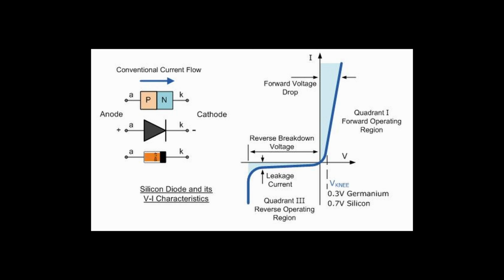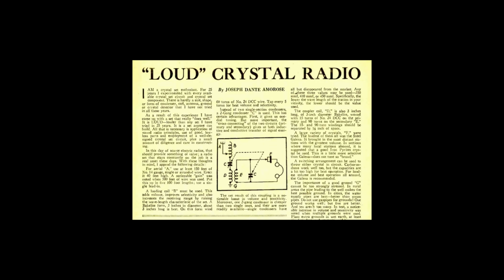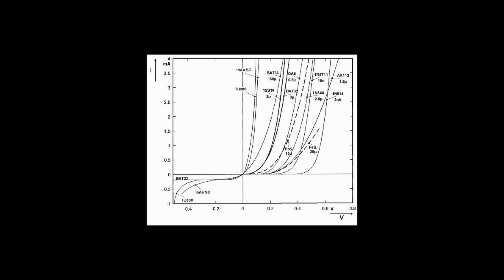My point is that no matter what's happening in the detection process, the diode's being a diode. It's conducting more in one direction than in the other, and it's doing it at a very small signal level. The forward voltage tester in your meter might be a great way to roughly identify whether it's a silicon or a germanium diode, or get a general sense of the cut-in voltage. That is, it's indicative that this might be a more sensitive diode. But it's not going to tell you about that really small voltage stuff around the origin.